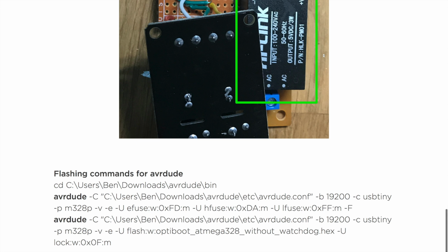So I disabled this one, and I have a thing on my OTA that, on getting a reset command, goes into bootloader. It's just a piece of code calling the same function that the bootloader has here, and it's going into reset state, and the bootloader is loading and waiting for the packets.